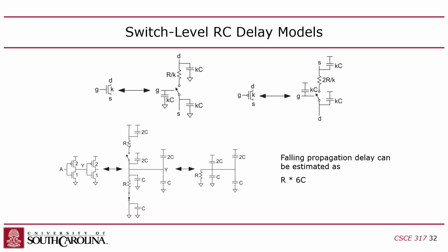Okay, so now if you take this circuit and you simplify it, we're going to get rid of this guy because it's a capacitor that's got ground on both sides. Get rid of this guy, keep this guy, keep this guy, get rid of this guy because the transistor's off, so I don't care. He's disconnected, right? Keep this guy and keep this guy.